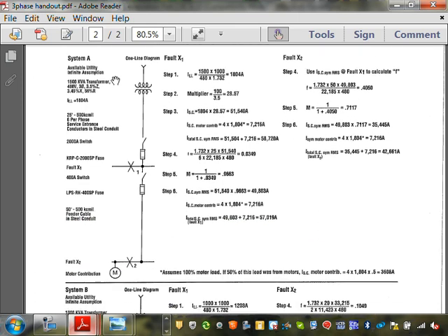The first step you have to do, if you have a transformer here: the reason we do a short circuit calculation is that in 2011, the NEC code book started requiring you to label your service, in other than dwelling units, with the available short circuit. Now, if your system is an engineered project, like a lot of them are, it will come with the engineers. If it's not, online, Bussmann and a couple of other companies have a little calculator where you can enter a couple of numbers and it gives you the short circuit.